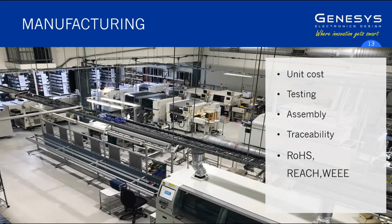And one thing that a lot of people don't think through is that the testing time itself could cost more than the unit cost. So you might spend a whole lot of time shaving a few cents or a few dollars off the physical cost of the unit. But if you neglect the testing, all of that effort in having a very efficient manufacturing design can be wasted if it takes you 15 minutes to test each unit and you're paying somebody quite a bit of money to do that testing. So that's a really important thing that needs to be brought to bear in the design.